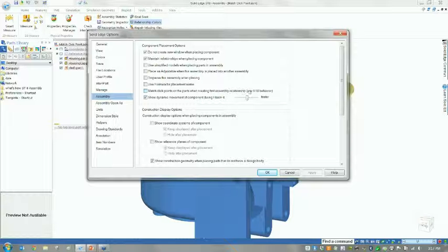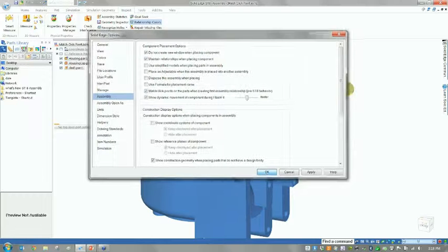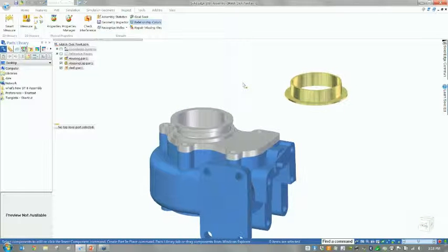What it's saying is, do you want Solid Edge to assemble like it did in version 7? So if you're in version 7 or 6 or 5 or 4 or all the way down, you're pretty much used to what I'm about ready to do. But then I'm going to show you what ST8, what Solid Edge 8 is going to do on that. Right now, the way it's shipped, it's unchecked, so it's going to act like version 8. I'm going to check it and on purpose make it act like version 7. Let's say you like it the way it does that, okay? So I'm going to make it act like version 7 and before.